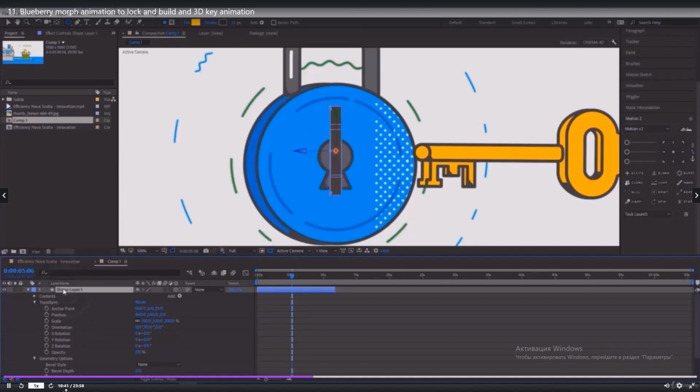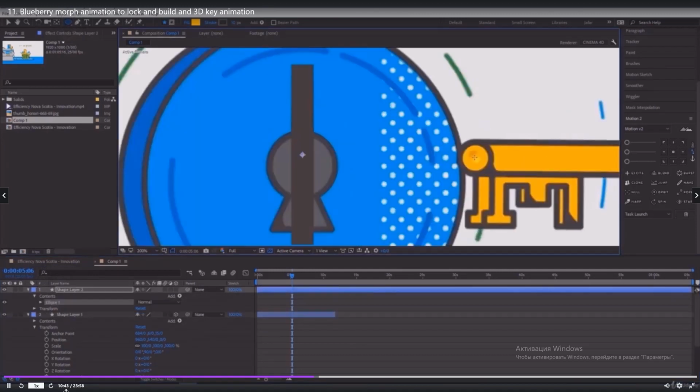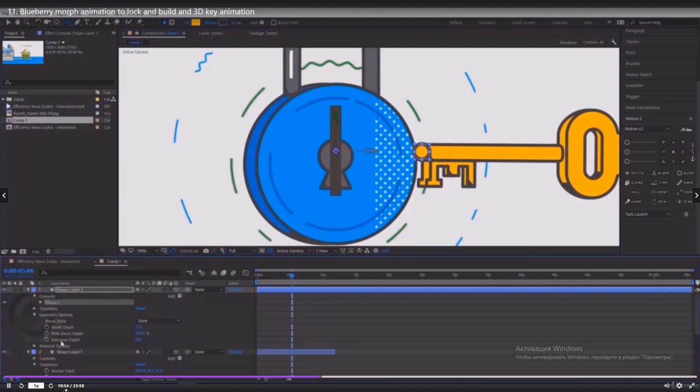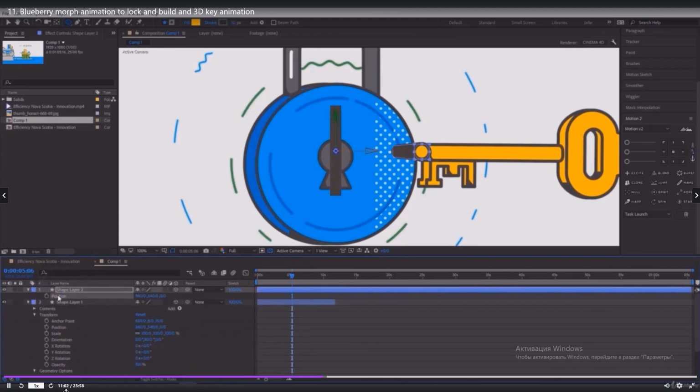Draw a circle like this. Then, turn the circle into 3D and from its Geometry tab, increase its extrude. For example, 1000. Then reset its position. Match its anchor point. Now go inside the custom view.